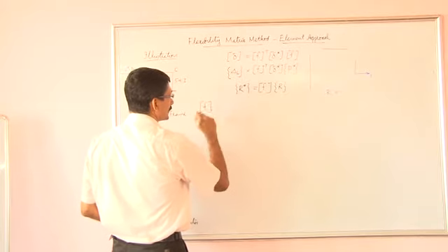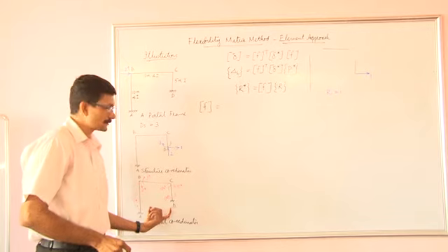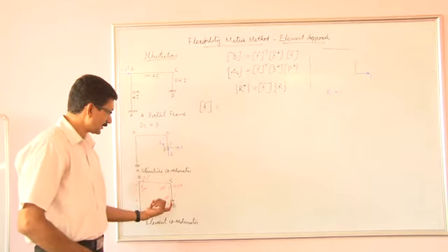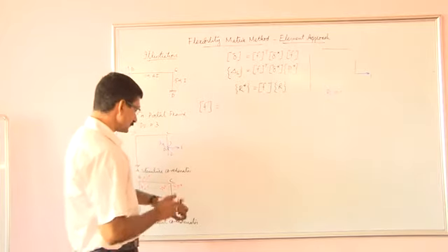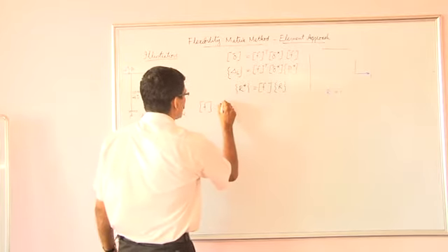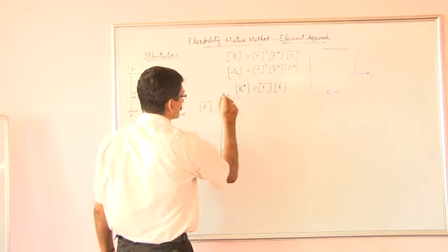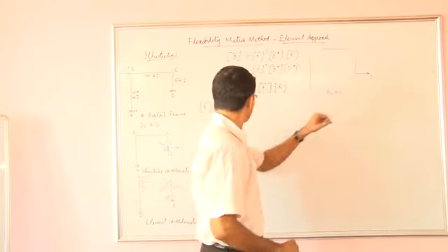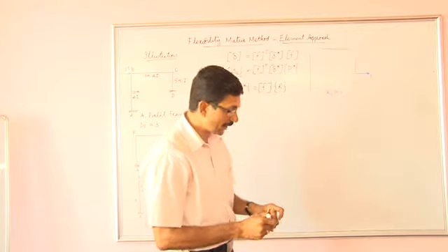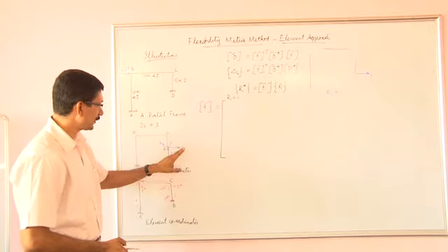We know that the size of F in this case would be 6 by 3. It is the number of element coordinates by the number of structure coordinates. The first column of this would be developed by setting R1 equal to 1. So when you put R1 equal to 1, that is, this force is equal to 1, and R2, R3 are equal to 0. R1, R2, R3 are nothing but the forces corresponding to structure coordinates 1, 2 and 3.